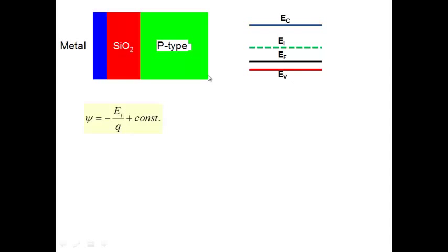So this is a system. If you look at it, metal oxide semiconductor, right? So in this system, we don't have any current flowing, right? Everybody agrees. As I go from this region in steady state; if you are in transient condition, of course, the capacitor gets charged and discharged, you have current flowing. But in steady state, I don't have any current flowing. Now, if I don't have any current flowing, all of you know that Jn we had written as n mu n dFn by dx, right? People remember this?